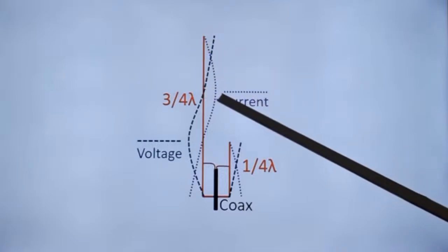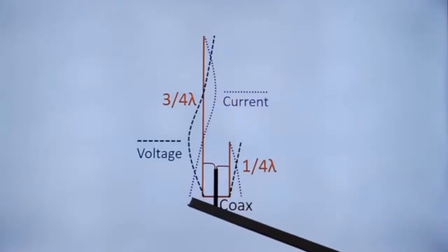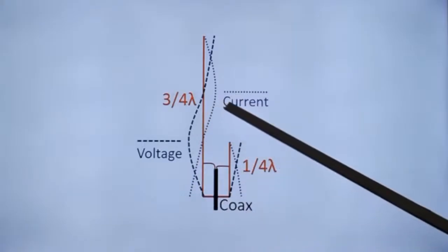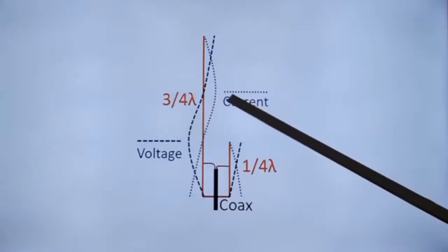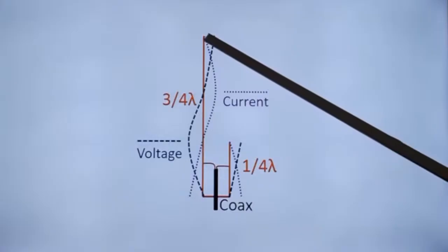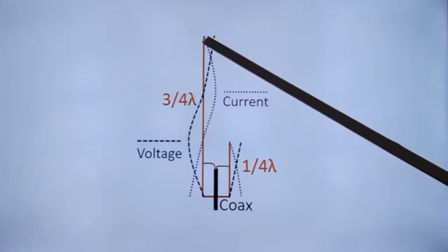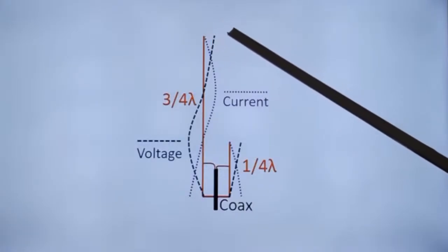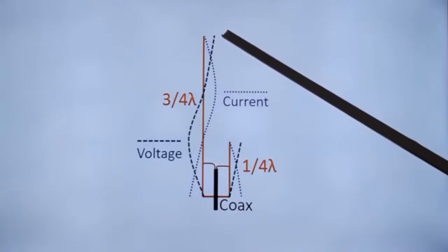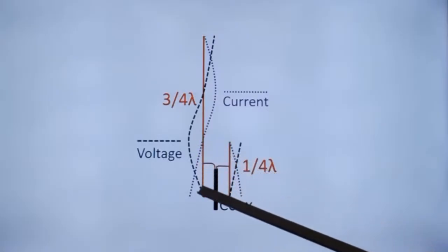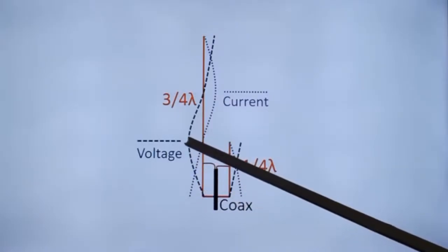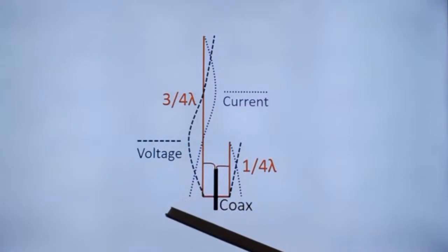This portion will be a quarter wave. Peak is at lower end and also at the quarter wave segment. And at the top, the RF current is minimum. Voltage is the other way around. Voltage is maximum at the upper end and for the lower 1/3. Here also the voltage is peaking.